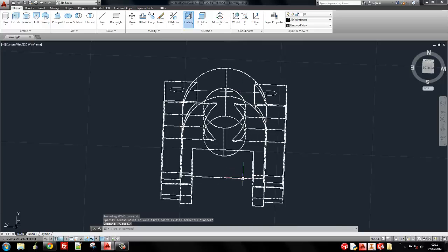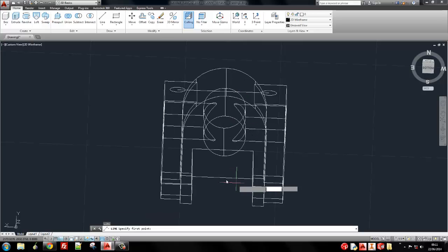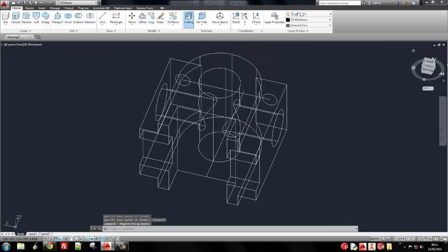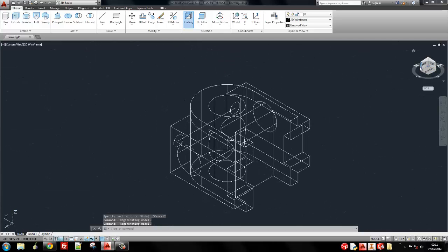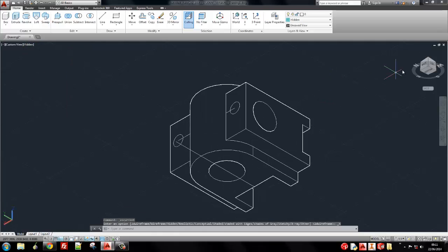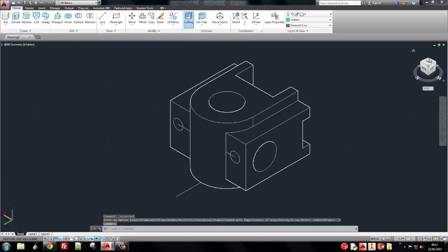So what I'm going to do is create another line from the center of this object straight up. Okay, this is all going a bit mad on my screen. Let's just orientate this a little bit better. I might turn on hidden detail so we get rid of the lines that we can't normally see. Okay, so you can see there I've actually drawn this line on the back of the face of the object rather than the front. All gets a little bit confusing in AutoCAD. It's not so confusing in Inventor, so hopefully when we get to that this will be a lot easier.